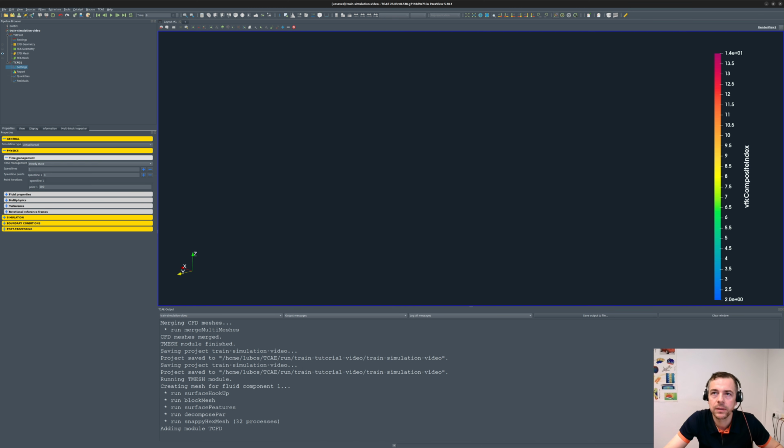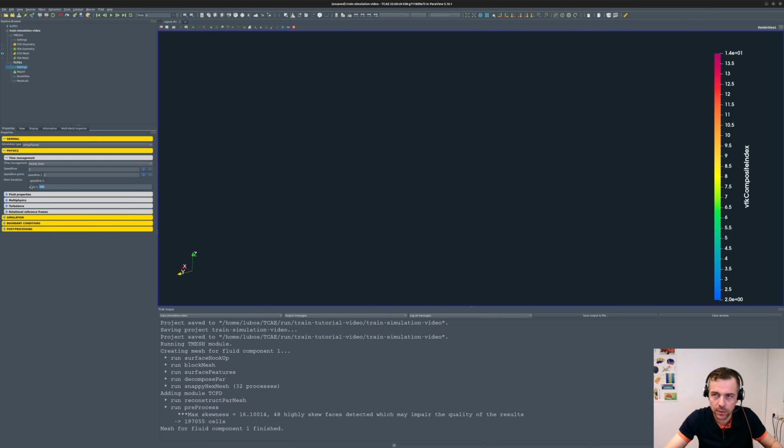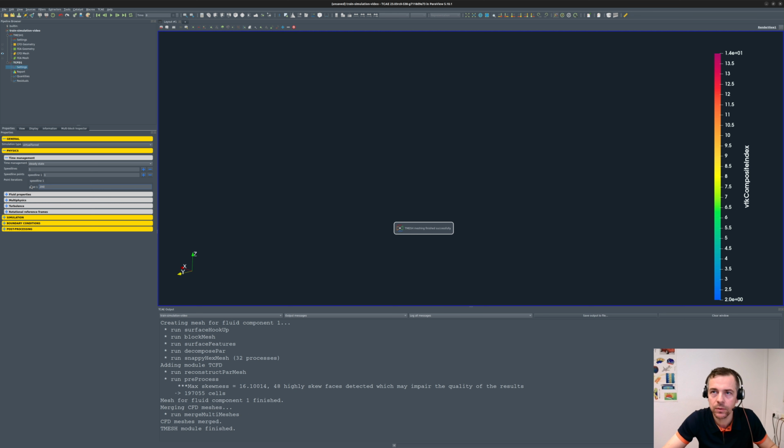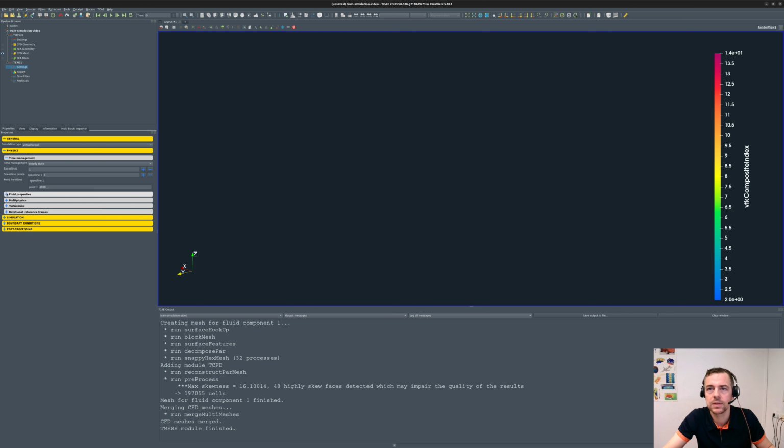In the physics, okay, I think I do not need to specify any special options. I need to do a lot of iterations because I want the algorithm to stop when the simulation is converged enough. So I'll say okay, I need to see 2,000 iterations, but we will not reach them because it will be stopped by the convergence check. But let's do that. I want to change the fluid properties. There is the air, incompressible, simulation, turbulence.